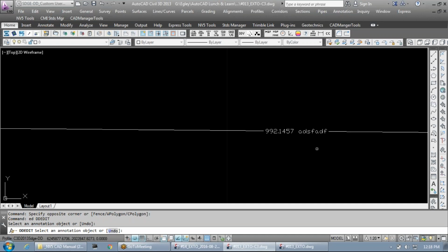So a lot of our construction lines, those layers should be frozen. But curbs and sidewalks, you should pretty much never freeze those, right? You can turn them on and off, but don't freeze them. It's that important planimetric information.